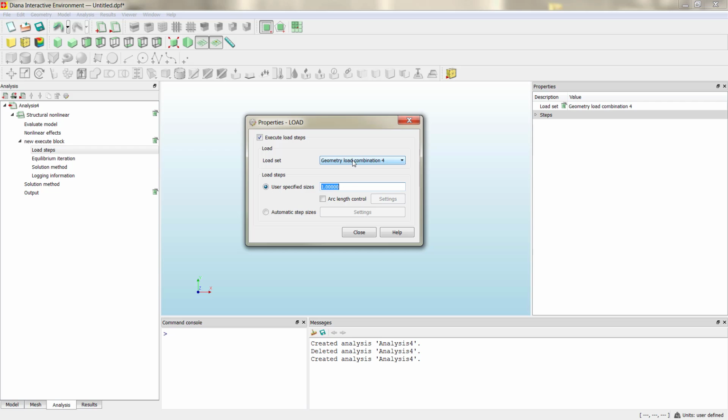So our intention is to apply this load one time. To do that, you can apply the load in one step or in different steps. If we want to define, for example, 10 steps, we need to discretize the load in different steps, and then we have to divide one time by 10. So that means 0.1 times the load each step. And then here you can also define different discretization.